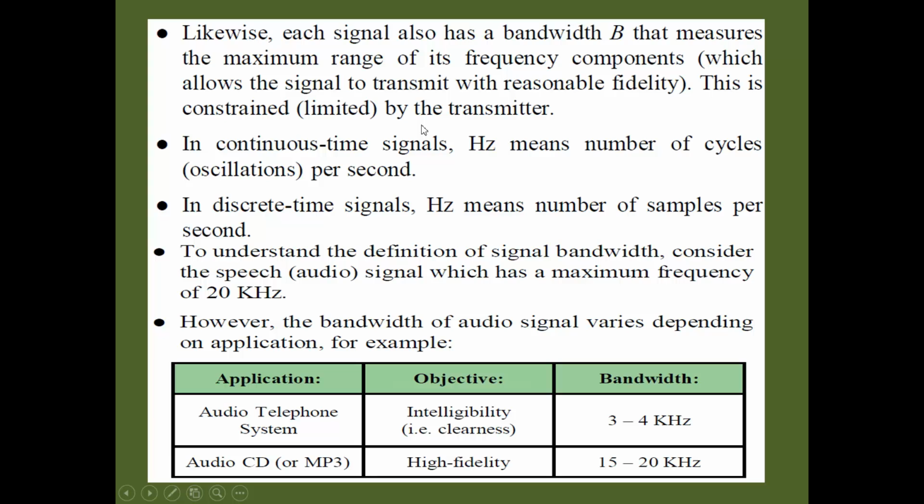Sometimes we can also band limit the signal, so that we can meet the requirements of the sampling theorem. We all know what the sampling theorem is. The digital signal can be reconstructed back if the sampling that we are doing is at least twice the maximum frequency component present in the signal.